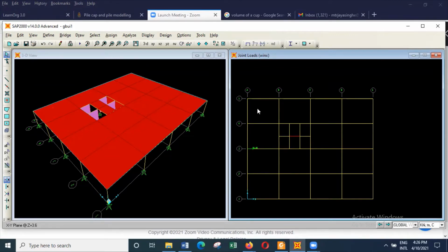In addition to that, you will get a load on the facade. So in addition to these loads, there can be a load on the facade, and there can be openings also. So I consider that the facade will consist of something like a 200 millimeter thick wall of density 20. After allowing for openings, I'll consider a height of 2.5 meters. So the facade load can be about 10 kilonewtons per meter length.